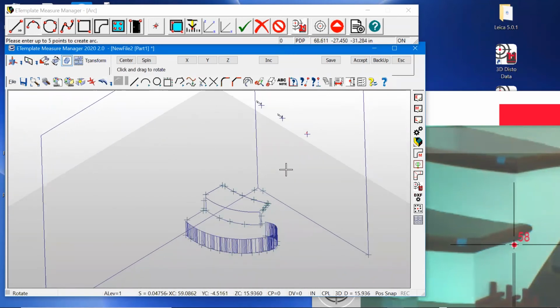of the staircase. Now, in some cases, I've had guys that have asked me if they just want to take points on the front edges or front corners of the staircase, if they want to offset a certain distance. They can use the markers to do that as well if they're bringing a railing system down and they want to know the connection points or where their balusters are going to come down. They also want to know just the radius of this turn. They can capture just that radius if they want to do that and just have it projected to the floor so that they know what the radius is. So there's a variety of things that you can capture as you're doing this very simply.